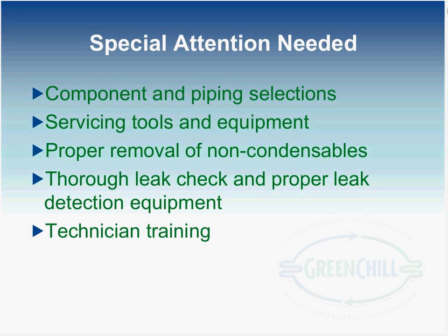But what I was talking about earlier was component and piping selection. With the pressures seen with use of CO2, this may mean going to something like K-type copper or valves that are rated for 600 pounds or more. Outside of this, it's pretty common now with the introduction of R410A in the industry. Most suppliers have re-rated their components for the higher working pressures. Some of the items to pay close attention to are the proper sizing and selection of the relief and regulating valve system with CO2, as prescribed within UL 1995.